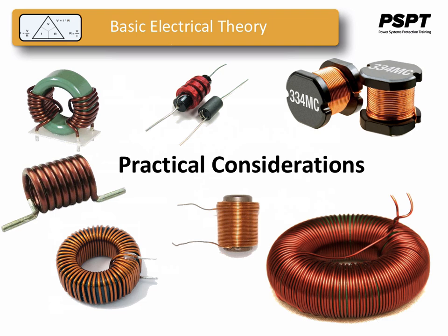Interference. Inductors may affect nearby components on a circuit board with their magnetic fields, which can extend significant distances beyond the inductor. This is especially true if there are other inductors nearby on the circuit board. If the magnetic fields of two or more inductors are able to link with each other, there will be a mutual inductance present in the circuit as well as self-inductance, which could very well cause unwanted effects.